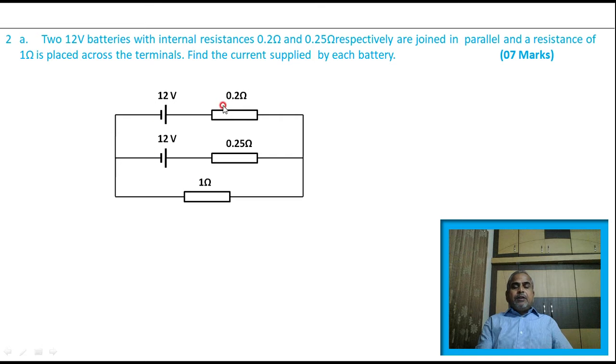Therefore, you can observe the given circuit. Here you have got two independent loops. Therefore, you have to choose two unknown currents in any part of the circuit you want, and you can mark the current direction in any direction you want. But the usual convention is that the 12-volt batteries are supplying the currents. The current is supplied by the positive terminal.